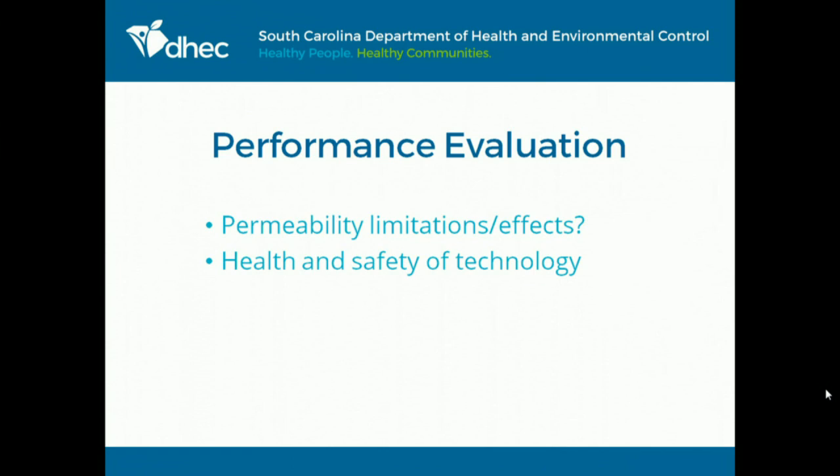Health and safety of the technology. Sometimes you discover safety issues in the field. One of my sites, they were doing chemical oxidation technology next to a wastewater treatment plant, and they forgot to vent the aquifer, and it was an exothermic reaction, so the foundation of the wastewater treatment plant building cracked. That was a good thing to learn.